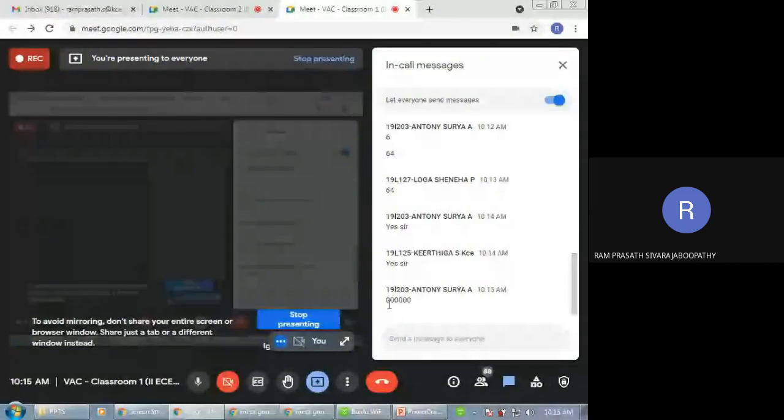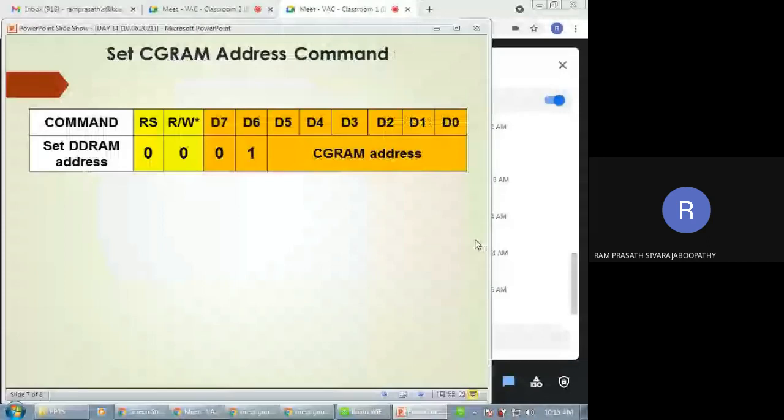Very good. Shall we start writing the program? What about the value I have to write? Substitute it and tell me. The CGRAM address is 000000. Substitute it and tell me to which address I have to start writing the 8 bytes.